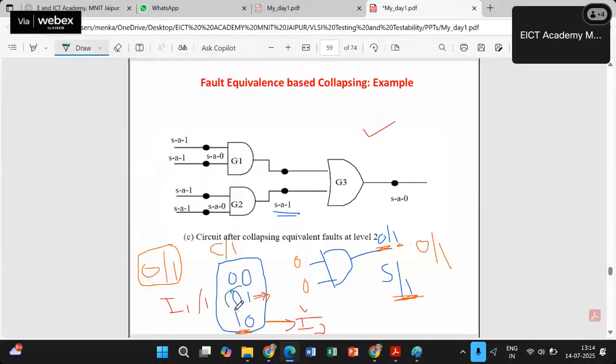That common input is the subset of what C stuck at 1 can have. Likewise, I2 can be detected and C1 can also be detected with the help of the 1 0 input. So it means I can remove C1 as fault dominance, because C1 is dominating. You can see the test pattern of C1 is a superset of I1 and I2.